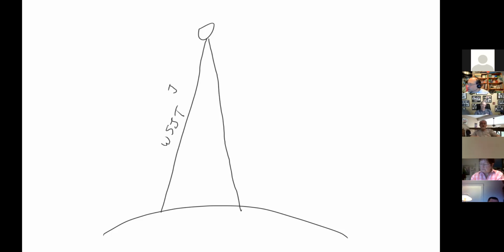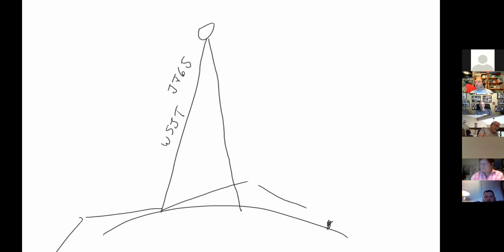One of the modes is JT65. That's one of those things that's used for moon bounce. Another one is that since we have these weak signals that are propagating through the ionosphere on different frequencies, we can actually pick them up from station to station on the surface of the Earth. And it takes almost no power to determine what propagation looks like. So they're used for propagation beacons.